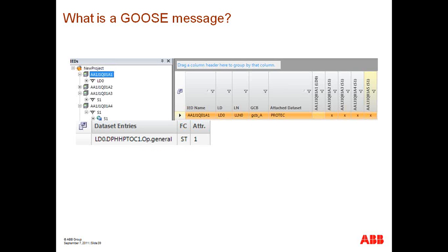When looking at the engineering process, essentially you configure your GOOSE message and what's going to be delivered as part of it. Based on the system tool you're utilizing, it's just a matter of checkboxing, or different tools from different manufacturers have different mechanisms, but essentially you have to make an association between the devices that you want to subscribe to that particular message and the message itself.